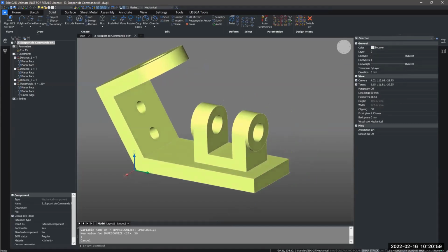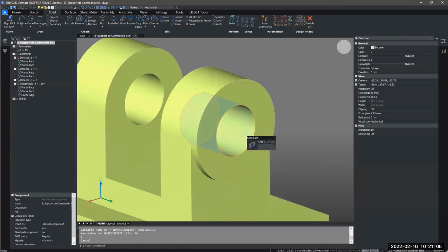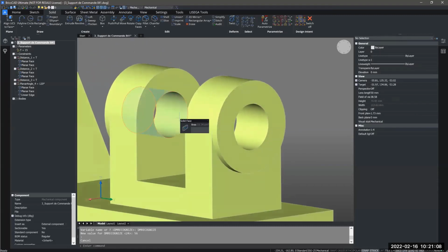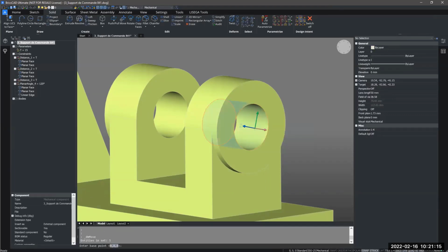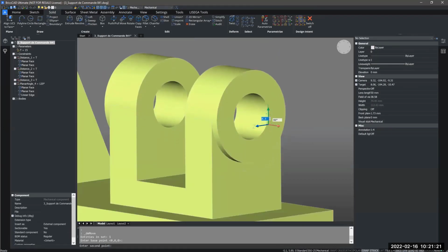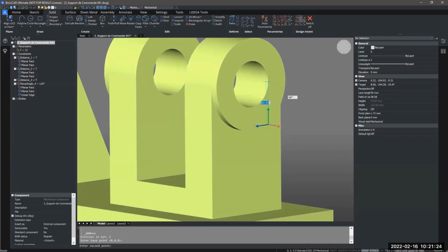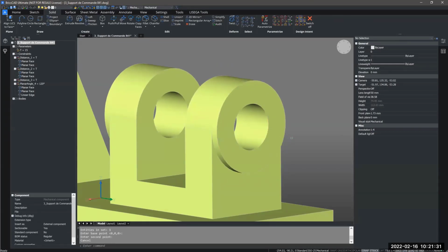Also, having coaxial surfaces enabled means that, like these parts, they will share the same center. These holes here from previously will also currently share the same center. So if I, for example, use the move command on this, I will just place this here, and I can see I'm only moving one of the holes, but you can see both of them will move together. This is the result of the design intent, then, keeping them as having the same center.